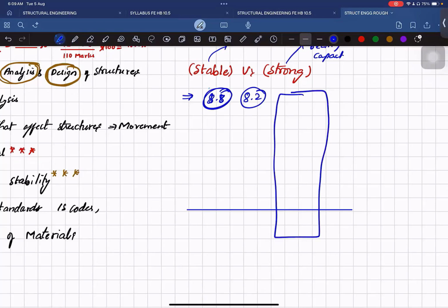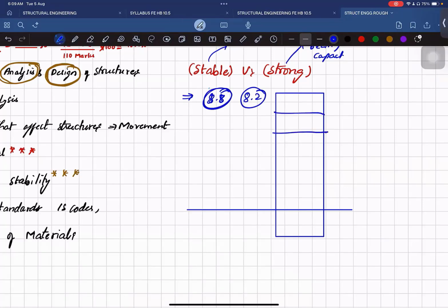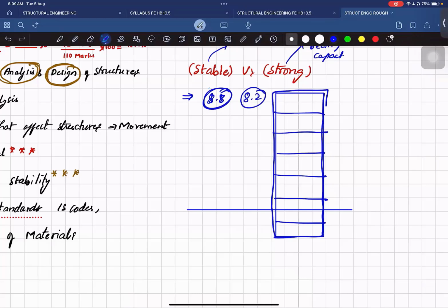if it was a multi-story building and they have constructed it very strong. They use M40 grade concrete, they use high strength steel, and so on. So they made a lot of efforts. But they did not worry about the soil on which they constructed. Suppose this is the soil in which they constructed the building, where they laid the raft foundation or so on.